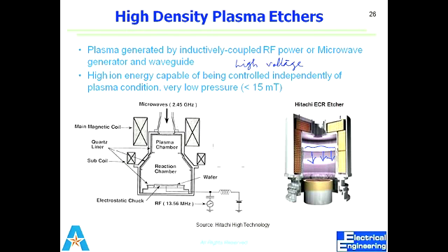Any question about the dry etching before we move on? Because I have 10 extra minutes, we can discuss the next topic as well. Any question about the dry etching? Which is preferred, high density at low pressure or low density at high pressure? What method is preferred? It depends upon your application, but mostly, let's suppose you have high density plasma, in that case you won't have very good control over the thickness, if you have very small thickness, because the etch rate would be high here.